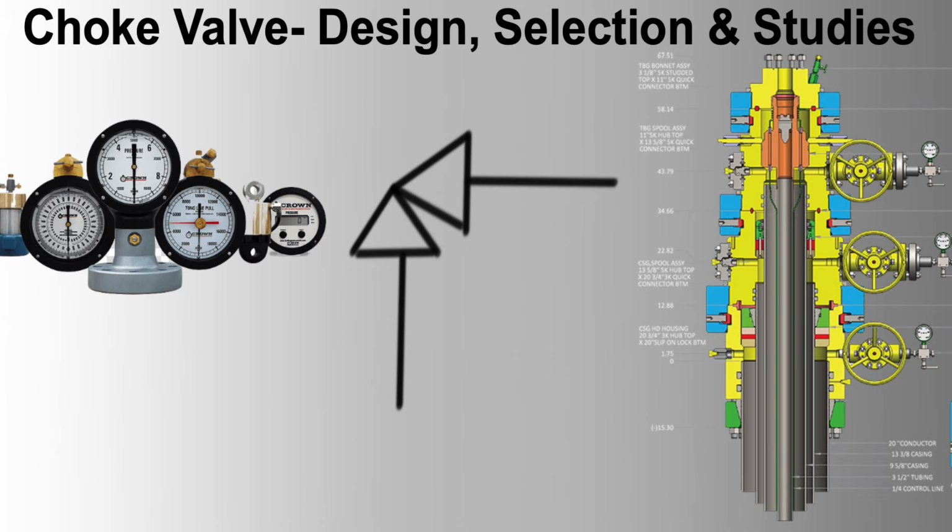Equal percentage, best for applications with varying differential pressures, ensuring smooth and predictable control. Quick opening, useful for emergency shutoffs, but less precise for normal flow control. 2. Orifice size, adjustability. Choose valves that allow for adjustable orifices for varying flow control needs. Sizing. Ensure orifice size matches the maximum and minimum flow requirements to avoid cavitation and ensure stable control.